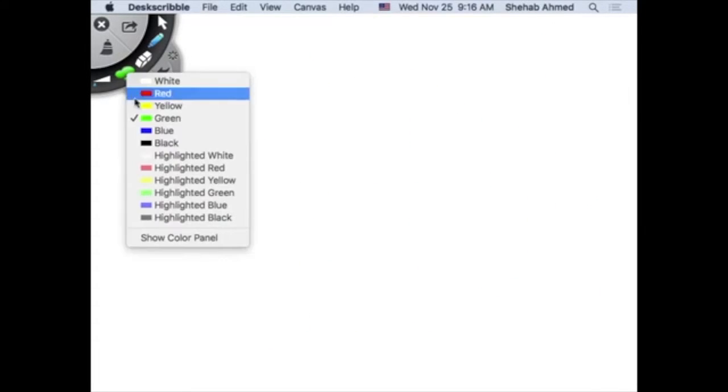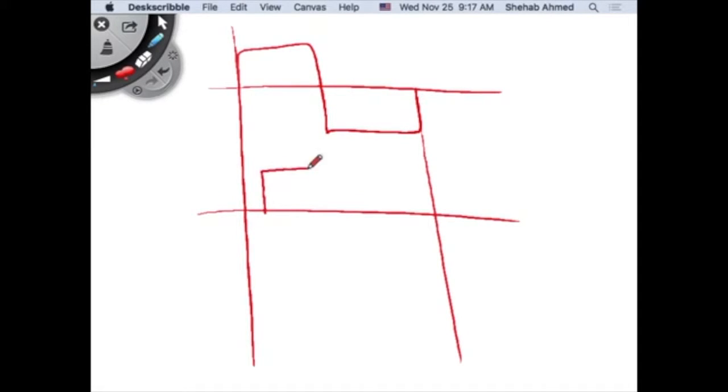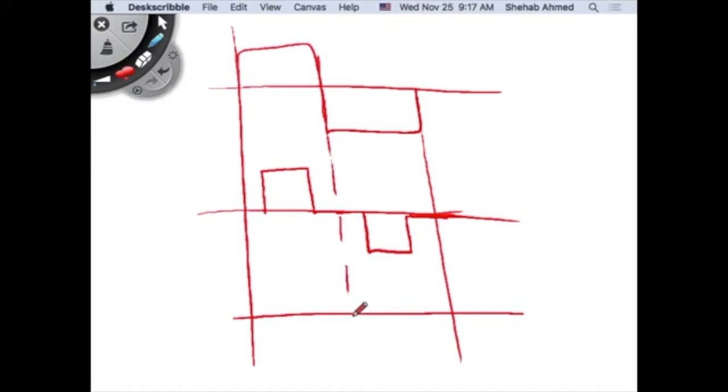We will look at the equations for all this, but they started with this, then added zeros. Then they realized that this is a nice trick to play with. If I add some zeros here and control my pulse width, they realized it's interesting. I can get better harmonic content. Fine, I have to raise this value of voltage, right? Because if I want to meet the same RMS value, I will have to, of course, raise this. But they found a nice trick.